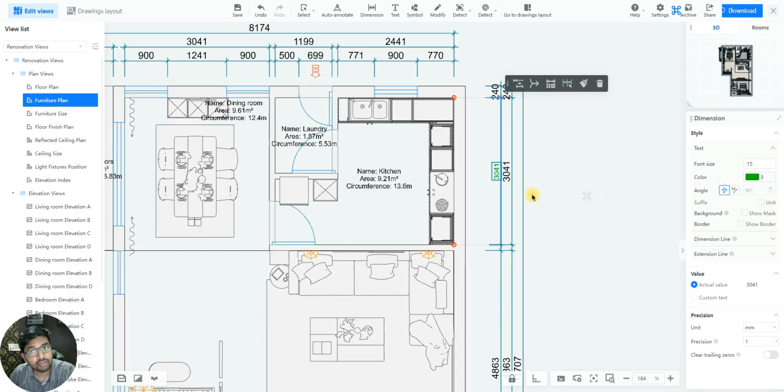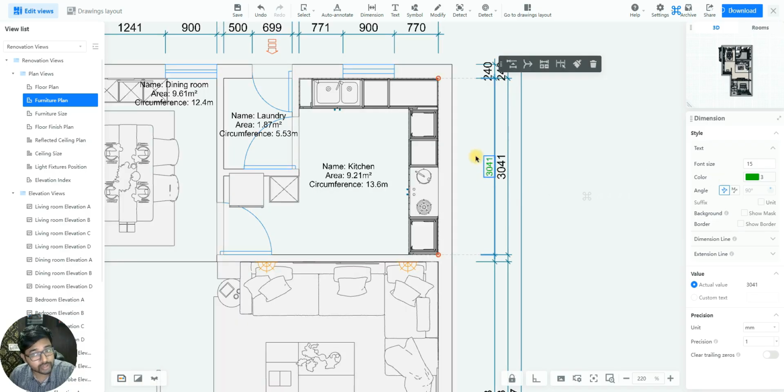Not only that, if you notice right now, all your dimensions here are aligned to the dimension line, right? Just parallel to the dimension line. What if you want your dimension text to always be horizontal? This is what your angle here is. So right now it is parallel to dimension line. Make sure you click it to fixed angle and you can define the position of your dimension. So though your dimension line is vertical, I can make it as 0 so that your dimensions will be horizontal.